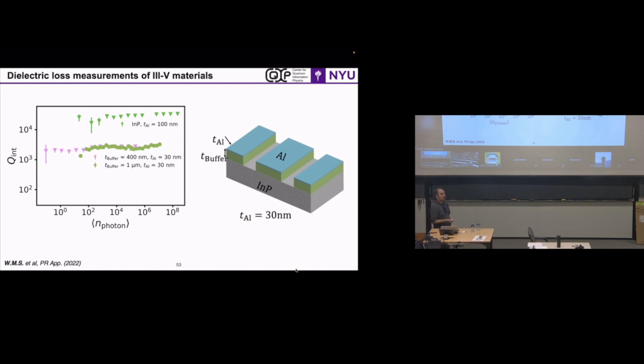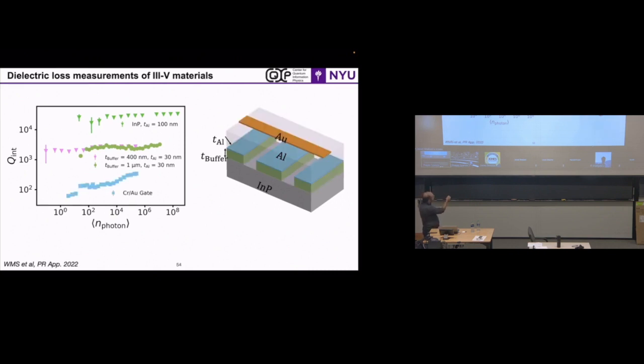We said, okay, what's the problem? Maybe the MBE material that we're putting on is bad. But then my student looked at this, and I said, let's make a full device. So we made a full device. It was an order of magnitude worse, because when we put the gate on top, it basically trashed everything. After the fact, we looked at this and said, this actually makes sense, because I have microwave, and this is gold, so it's dissipating. So basically now I'm dissipating everything out.